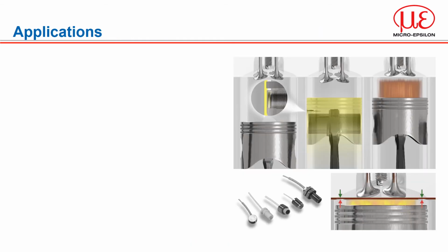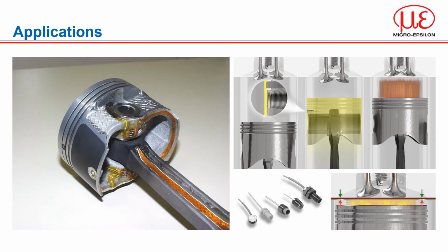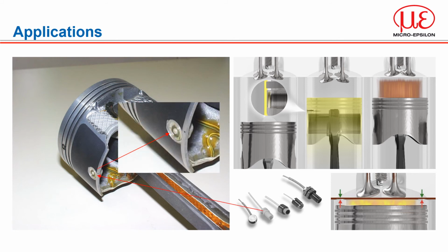Our ability to build sub-miniature sensors has opened up possibilities for customers to perform measurements that simply were not possible before. Our smallest sensors are literally 2 mm in diameter. We have many examples of eddy current sensors used in the development of engines, including looking at secondary piston movement and cylinder head breathing. The small shape and size of the sensors enables them to be mounted even on moving parts and in fired engines.